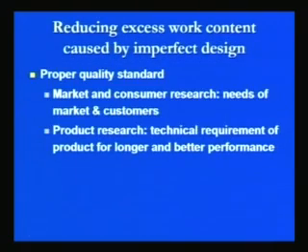The use of poor quality standards also leads to the excess work content. Like if the quality standards which have been set are on the too high or on the too low side, then in both cases excess work content is required. Too high quality standards lead to the extra care and extra time required for achieving the higher standards, while on the lower side, standards lead to the rejections of the product by the customers and frequent complaints from the customer side.